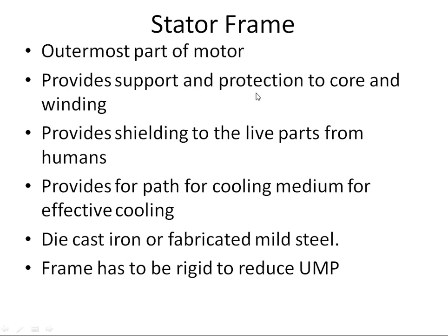The stator frame is the outermost part of the motor. It provides support and protection to the core as well as the winding. The winding is the most delicate part of the motor, because it is made up of copper, and copper is very soft in nature, so we must provide sufficient protection to the winding. It also provides shielding to human beings from the live parts of the motor, so protection is provided to the human being or surroundings.